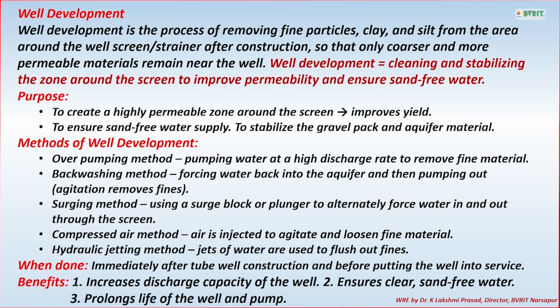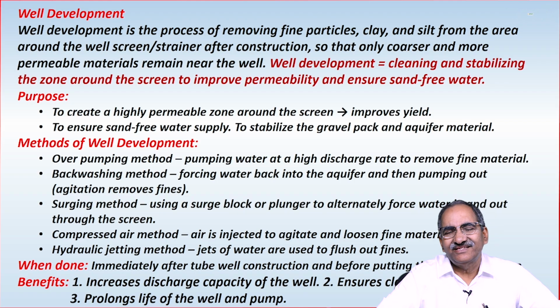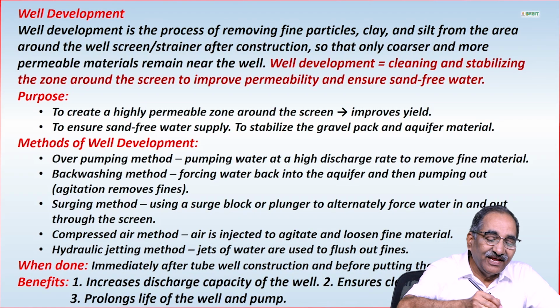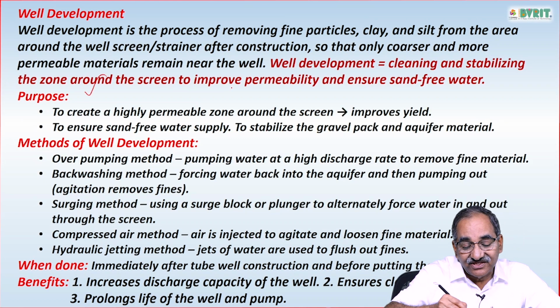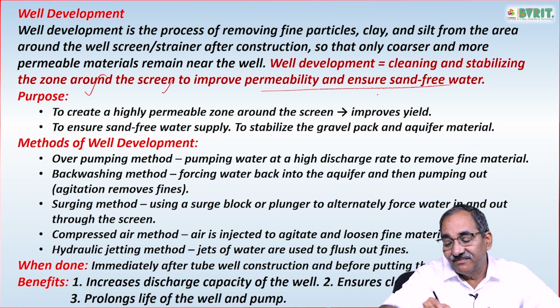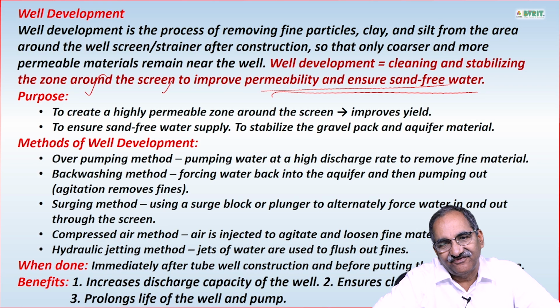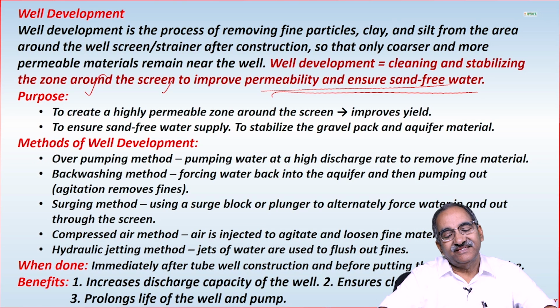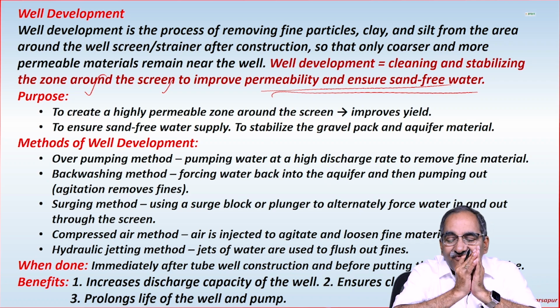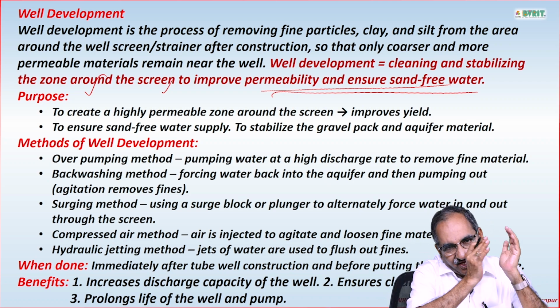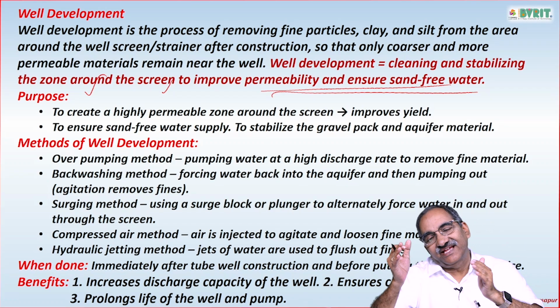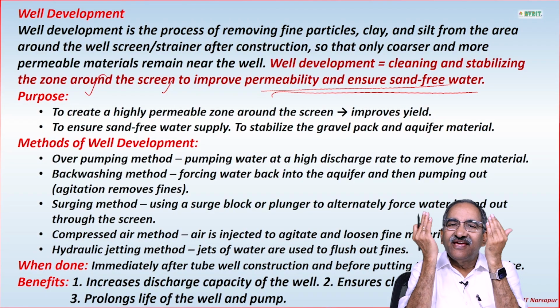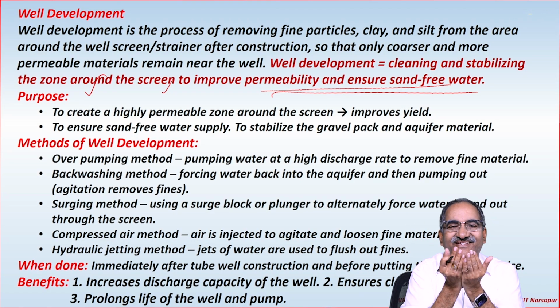One is well shrouding, the second one is well development. Well development is nothing but cleaning and stabilizing the zone around the screen to improve permeability and ensure sand-free water. Well development is the process of removing fine particles such as sand, clay or silt from the area surrounding the strainer.